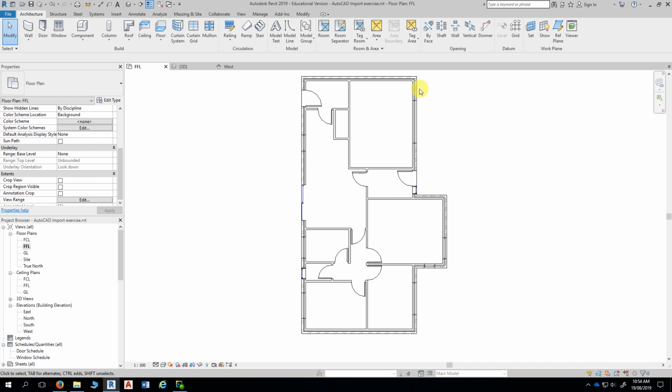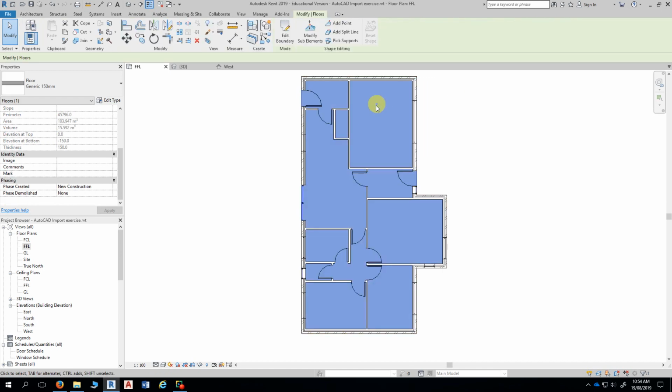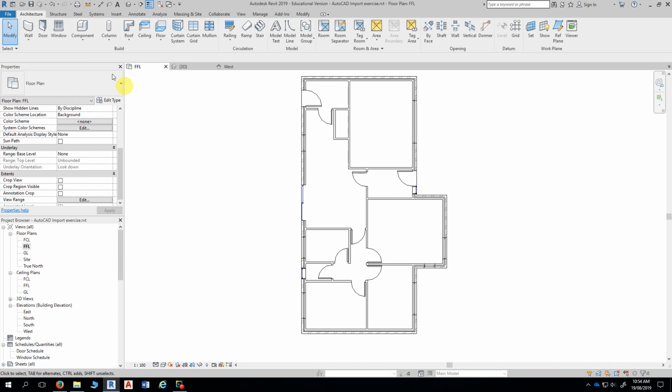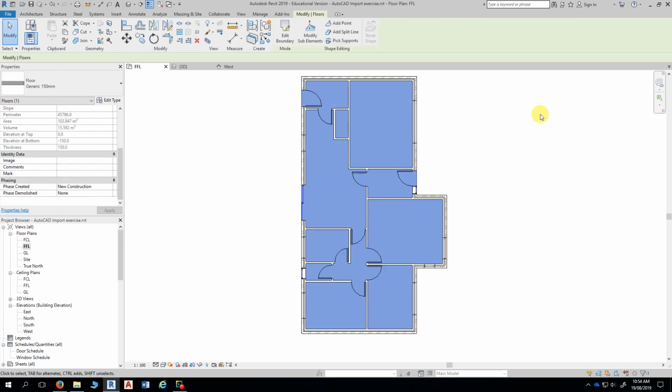I can go to the edge of it, hit the tab key a few times and then get it, but I can't select it by face. And that's this particular setting here. So if I re-tick that one, I can then click on it here and select it. So this is what's called frustration avoidance. All right. Okay.